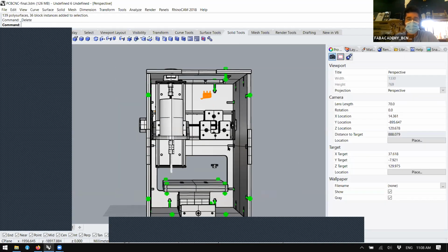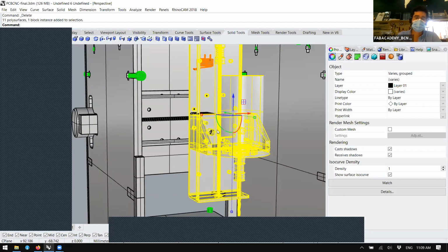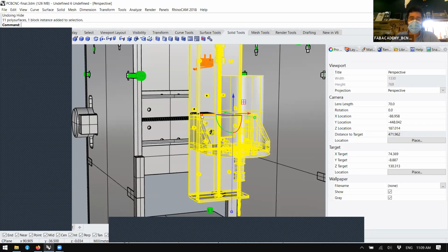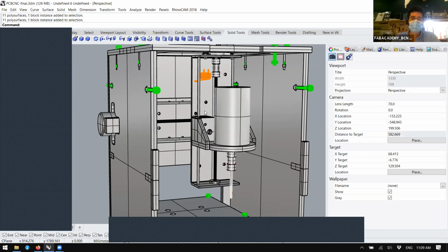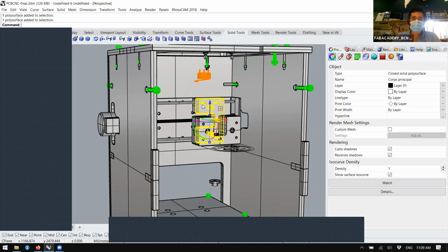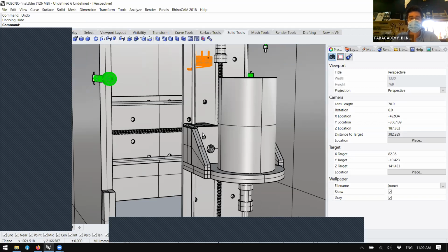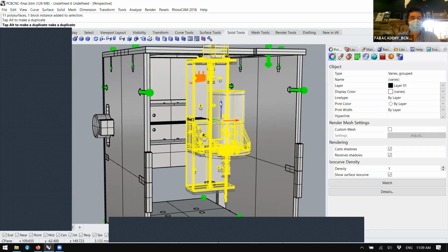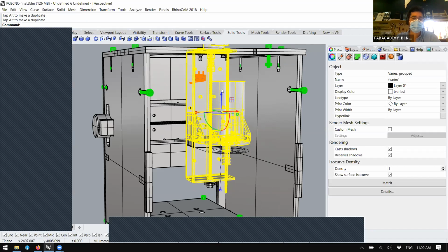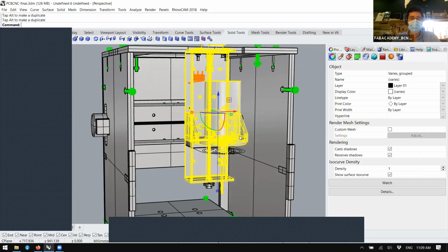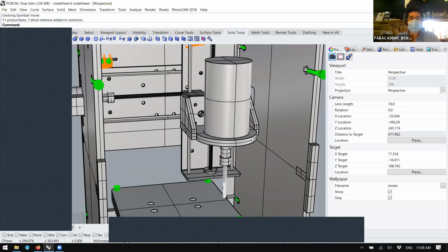Why? Because our initial thought is that once all the pieces reach here, we will see where we attach this slider. We will directly screw the back steel plate to the slider of the other axis. We can do it with these holes because this slider has a lot of holes. We will maybe mount it a little bit lower, maybe a little bit higher. We will see once we have the machine here. But these are design solutions that we don't worry too much about because they are really easy to fix once we have all the parts. We are mounting the CNC motor directly onto the slider, and we have made this.